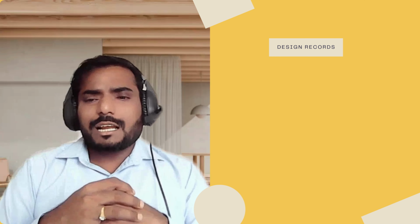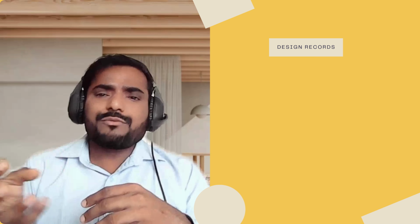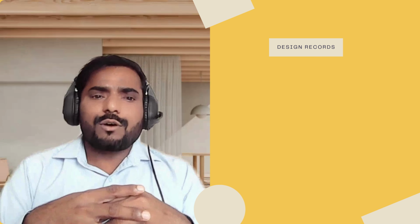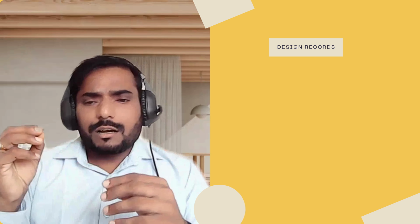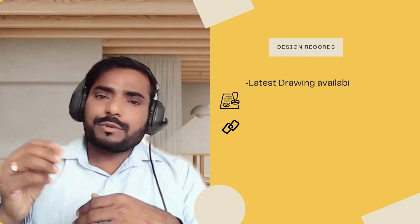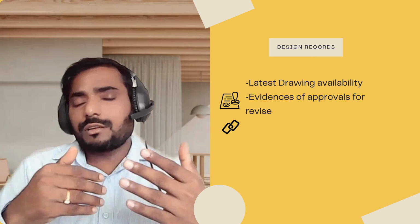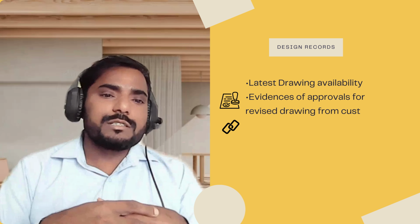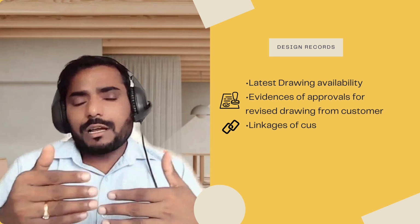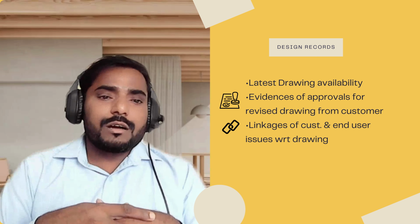If we talk about the elements of PPAP, let us start with the design records. When you go with the design record phase, I'm just covering a few of the critical points you should verify in that particular design requirement. First one, availability of the latest drawing, whether it is approved by the customer. This is very important. Sometimes they're not following the latest one; if they're following old revision documents and manufacturing the component, that will lead to an increase in COPQ and impact your production.